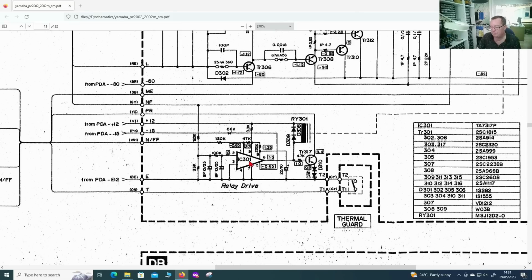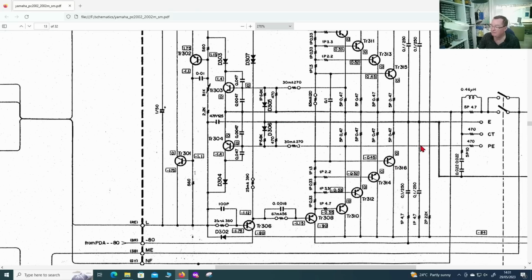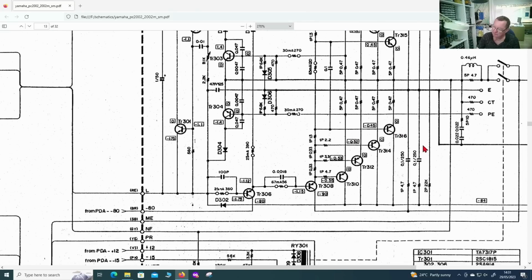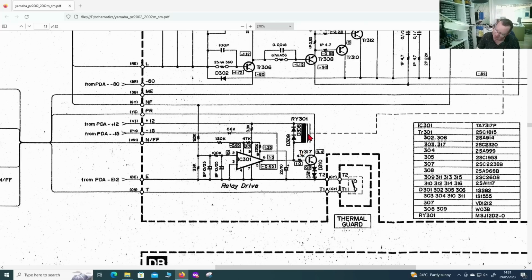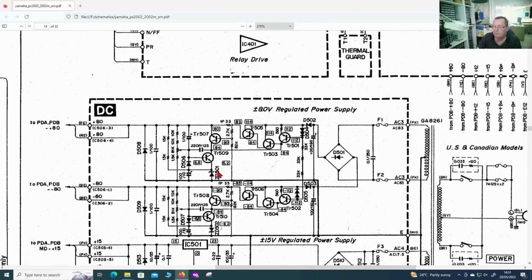And the reasons are twofold. One, the DC offset, if there is a DC offset here, could be positive or negative. So we also want this to switch the relay off if there's a negative voltage on here as well as a positive. That's why it's not just an op amp. You can also tell that the voltage here can be positive or negative. If you look at these capacitors, these are electrolytics, but they're bipolar, BP. There's no plus sign by them, yeah? If you look at some other ones, look, there's one with a plus sign, okay? It doesn't say BP.